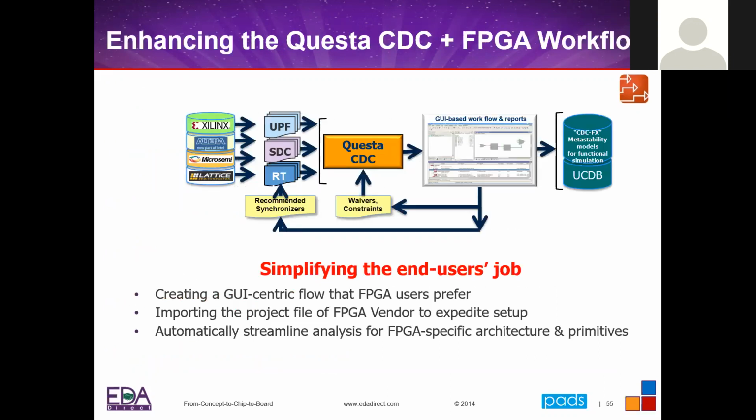It's very focused. So the workflow for this is you start with your RTL code. You can have your SDC constraints, your Synopsys design constraints. We do have formal libraries for all of the major vendors. So if you have instantiated gates, or things like the DCMs, the PLLs, et cetera, from the vendors, you're going to want to bring those models in so that we can understand what the functionality of those is, and then do this analysis.